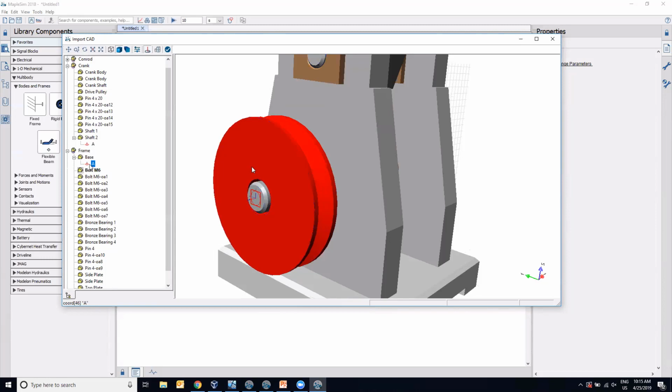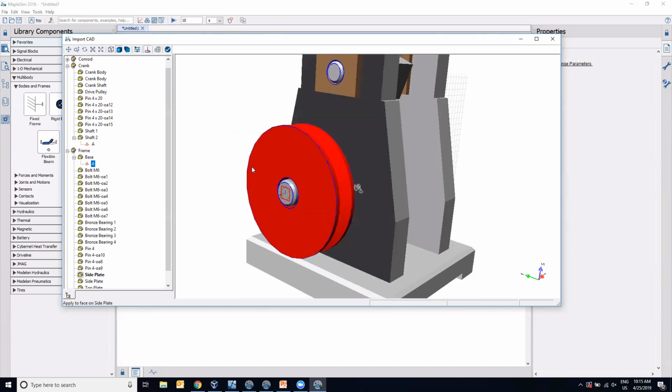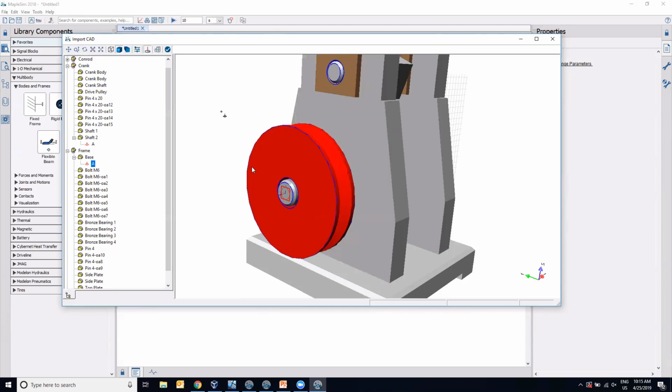And so this is going to give me essentially a connection location on my crank component as well as on my base component, where I can then define this rotational motion. I will also add one on my base. This is going to help me fix my base to the ground. So I'm going to change the name first. I'll change it to ground so I know that this is the one I want to connect to the ground.